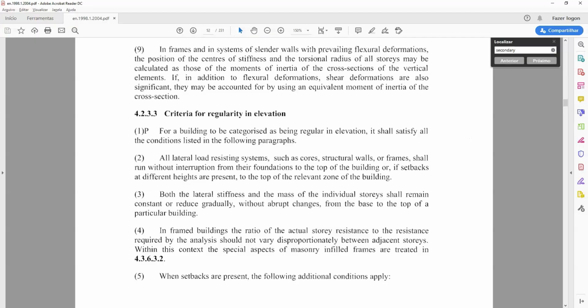Looking at our building, we recognize that the structural elements do not have significant section changes, and those that do, like the central columns, have very small variations. Furthermore, the changes in terms of mass are also insignificant, occurring only at the roof level due to the reduction in live loads and other dead loads. It does not appear that we have a building with any abrupt changes in stiffness or mass over its height.